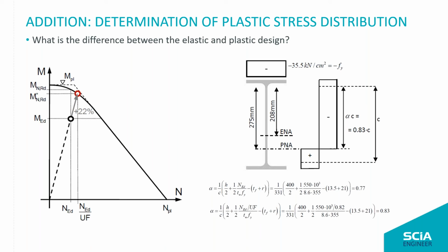And if we look at the actual plastic redistribution, where both the normal force and the moment get increased proportionally, we actually reach the true plastic neutral axis at a position of 0.83. That means that, from the moment with the My, we do have, let's say, 10%, a bit 6% of the section more under compression than before.